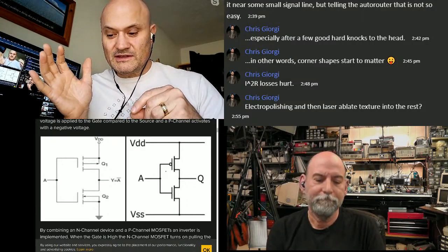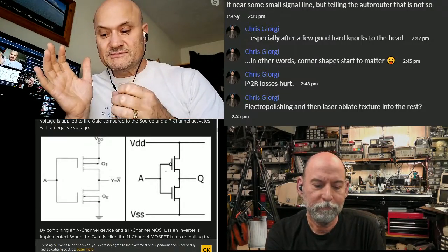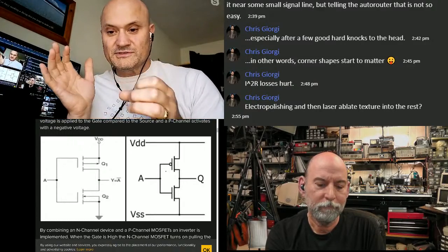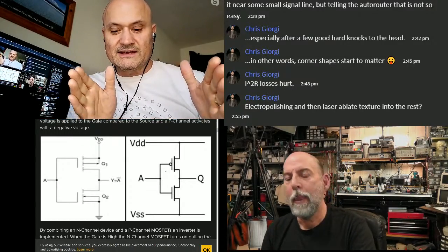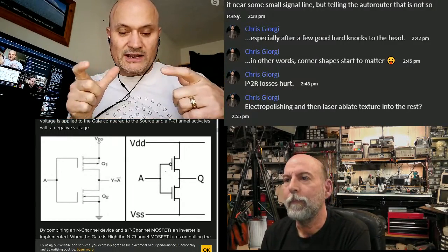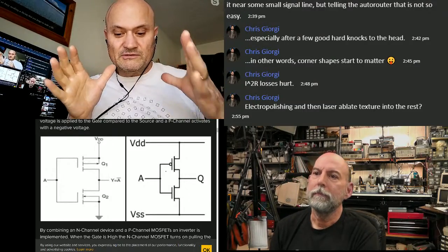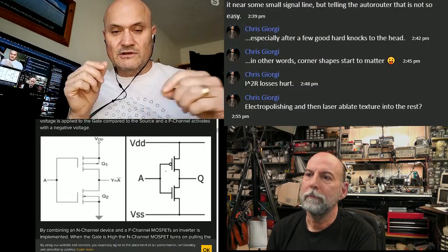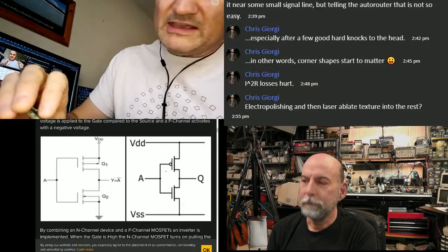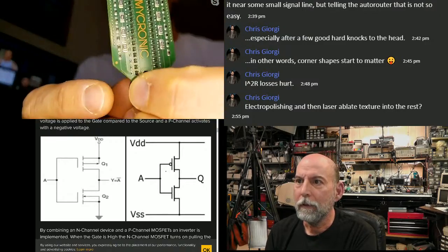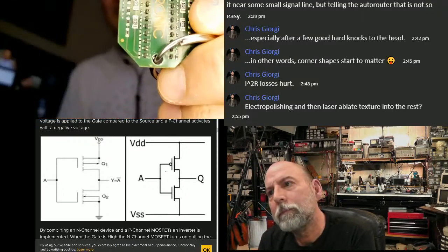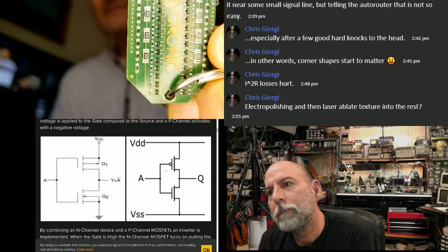The camera on the pick and place machine will examine where the fiducials are for every board that comes in on the conveyor, and it will calibrate the location and the position of the board so it places all the components accurately. So here's a very simple fiducial on this micronic keyring, that dot.